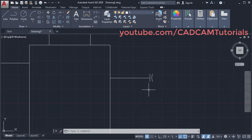Now it is looking smaller. We can increase the size using scale command. Click on scale, select this object, enter, then base point will be this midpoint, then give the scale of 1.3. To increase the size of the object, you will have to give scale more than 1. Press enter. Okay.